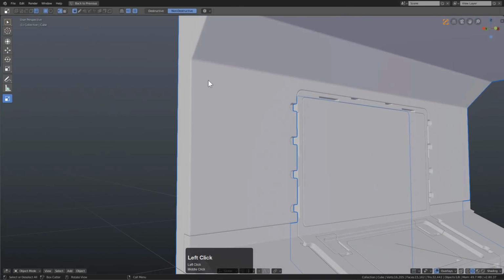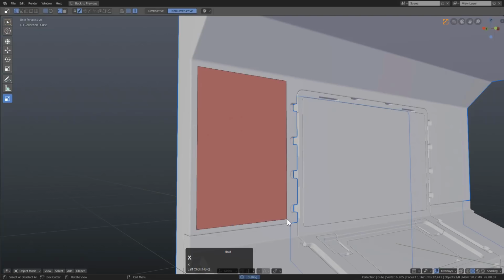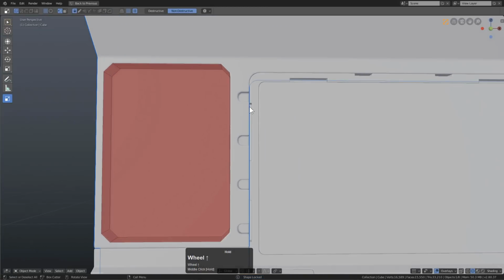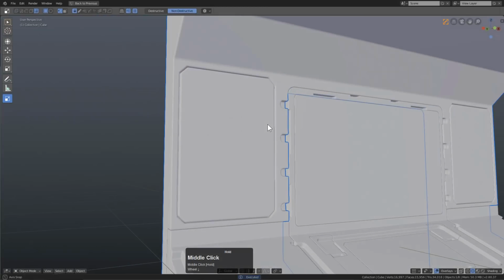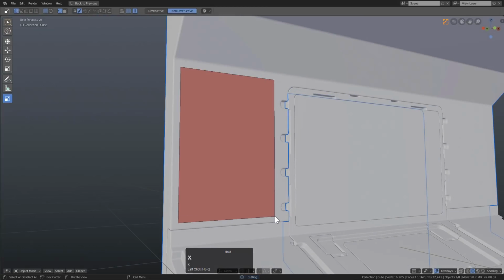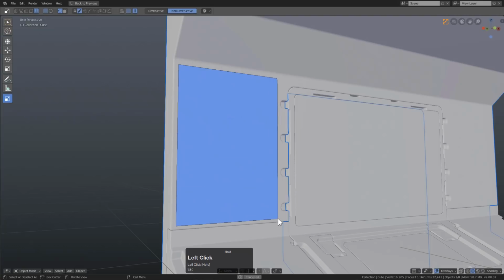My goal is always to just, in these videos, talk a bunch, show how I use Boxcutter, and I'm only pressing left mouse click. At this point I could press T, turn this into a panel cut if I want these two pieces to be connected, but panel cuts have always had a strange place, and it isn't right here. In fact, I don't want that. I keep pressing T. What am I doing? I actually want to press X and then press B.